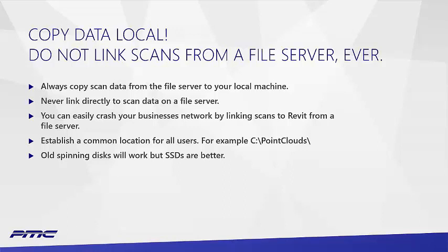Do not stream point clouds from a server unless you happen to be at a place that has built an entire enterprise around high volume streaming off a server, which almost certainly you are not. Don't connect files from your server shares. Don't remotely access them. Copy them local to your local computer before you attach them to CAD, Navisworks, whatever you happen to be using. All right.